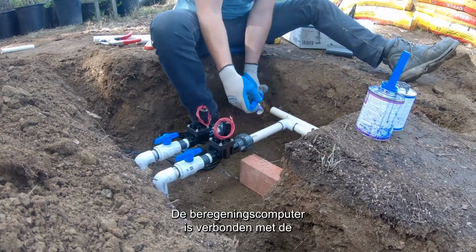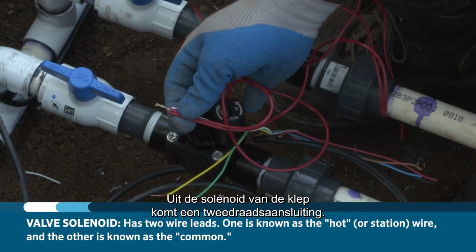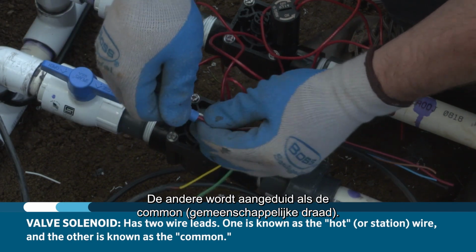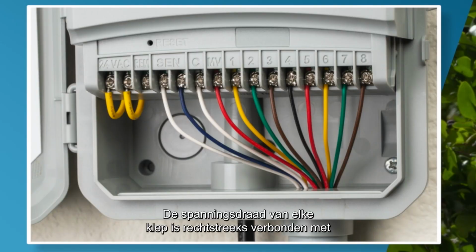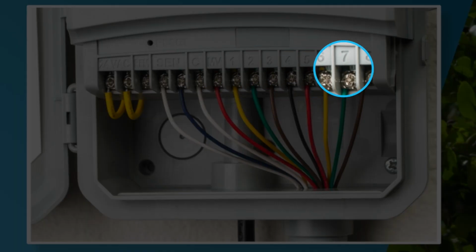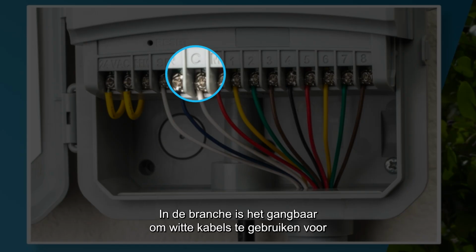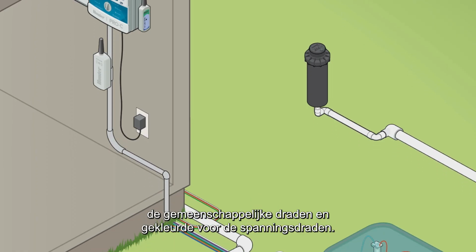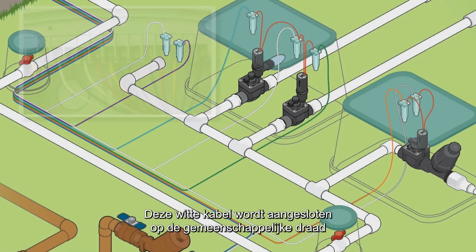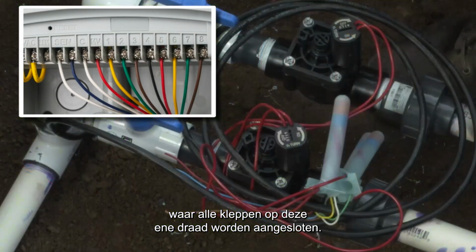The controller is connected to the electrical zone valve through insulated heavy-duty wires. The valve has two wire leads coming out of the solenoid. One is known as the hot, the other is known as the common. The hot wire from each valve is directly connected to each of the individual station terminals at the controller, while the common wire is common to all stations. A common practice in the industry is to use white cable to differentiate common wires from the rest of the colored hot wires. This is connected at the common terminal at the controller and goes out to the field where all valves get connected to the single wire.